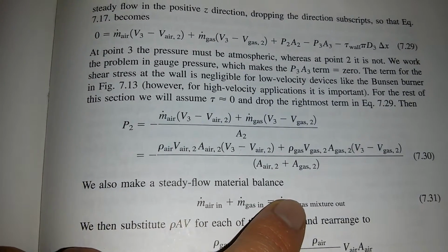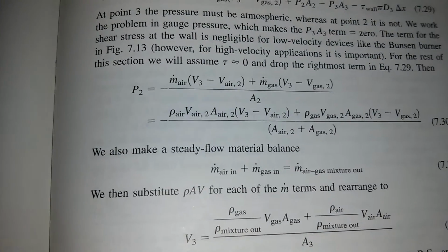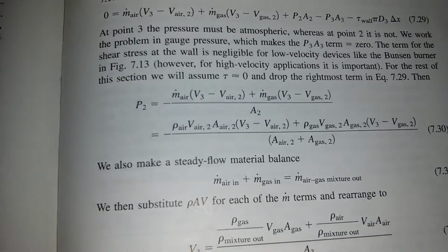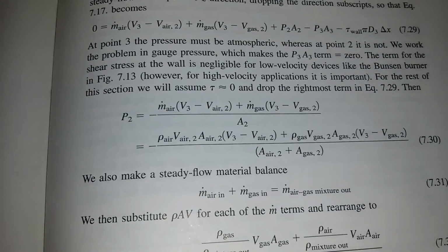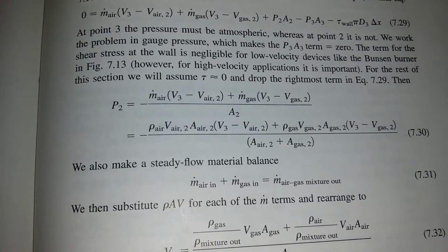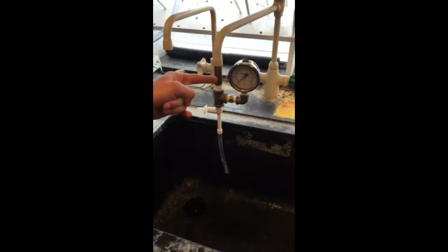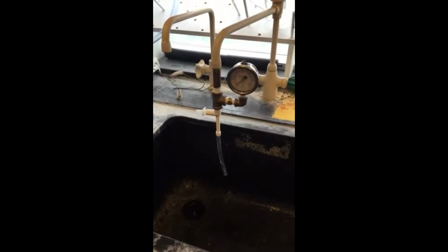If you switch the velocities, you will get a proper calculation, but you have to do the derivation yourself and relate it to the aspirator. But this is a nice start for the calculations and should tell you if you're going in the right direction. Right now, no water is flowing through the aspirator, so we're at 0 psi. But as soon as you start getting a flow, the pressure is going to go up.